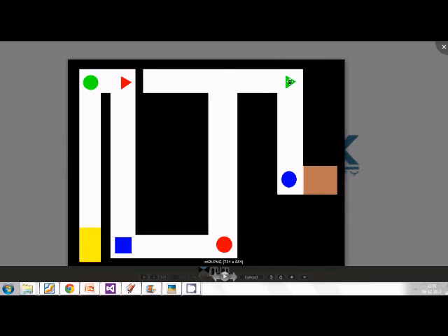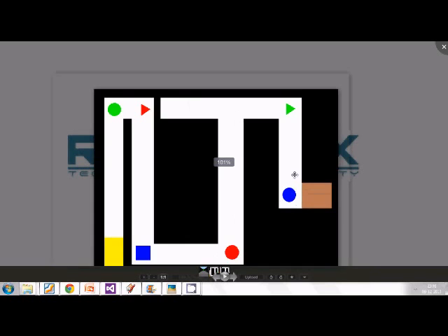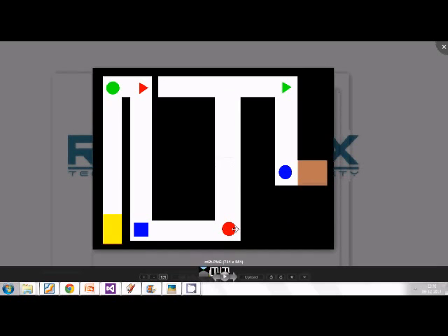From here, if I just follow the cursor, if I go down to here, and here I drop a horizontal line. I'll explain how to do that in a minute. So this is one point and this is one point. So again, this is assuming simplistically that there are straight lines and straight paths and all of that. So we have these 2 points, and then we just need to check which of these 2 points is directly connected to both of these waypoints. So this point is neither directly connected to this, nor directly connected to this, because there's black space between them. So this becomes our next waypoint.